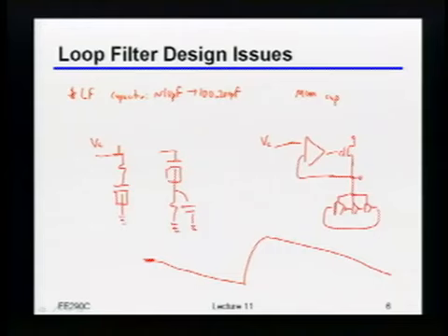If you do that with another cap, then you have this sort of game of how big is that cap versus how big is this cap. Now, indeed, you might be able to get that to work. Turns out this is another one of the reasons why people really started looking at more digital implementations, meaning where you somehow have the loop filter implemented as just an accumulator. Because there, a digital accumulator really does not leak, at least unless you did something really stupid, right?